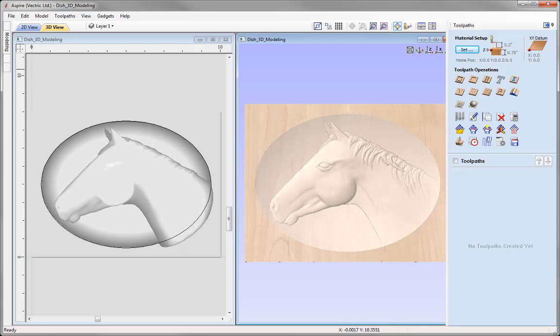Depending on the material and the size of the part you're tooling, you may need to do both a roughing and finishing pass. In a lot of cases with a dish model, you'll find that a finishing pass on its own will work for you. When you do a finishing pass, the only time that you load the cutter up is on the first pass. Typically, you don't want to bury to a nice deep depth and then run it along with the full force of the material on the tool, because it will snap.